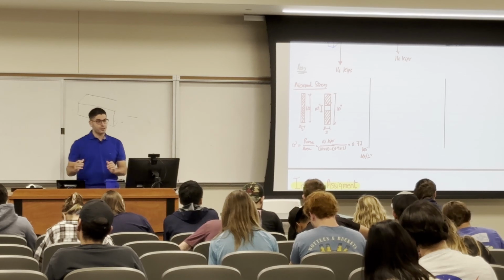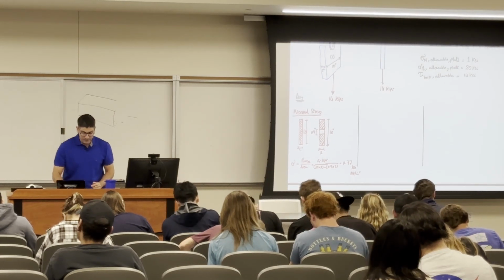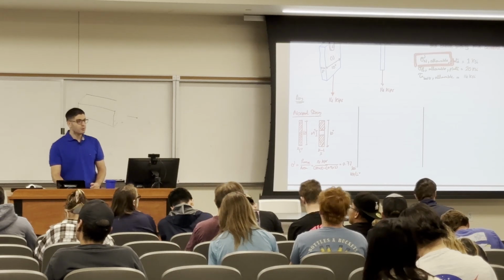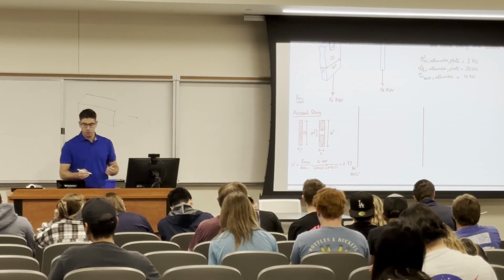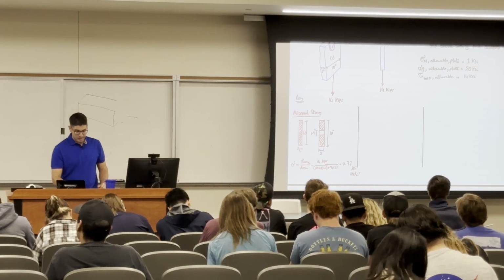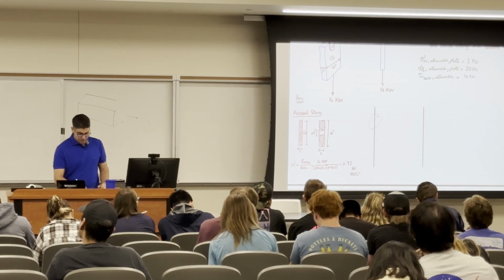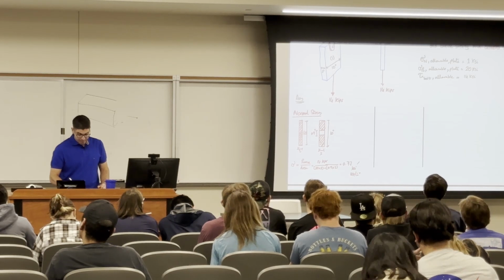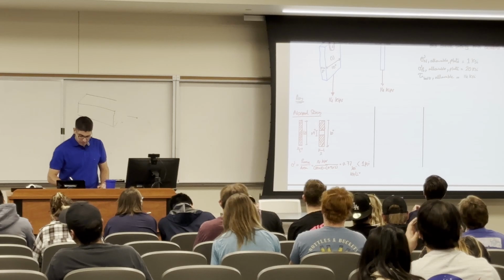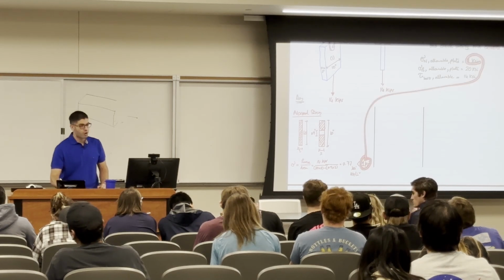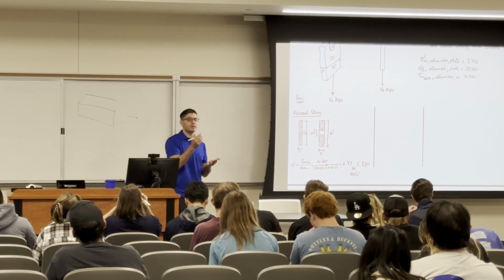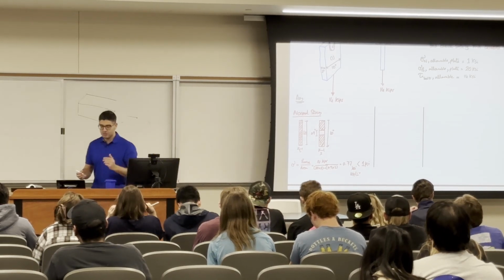Okay? I want to check the safety. So I will look at the strength, which is in the form of allowable. Allowable means accepted for the plate. So what's accepted is 1 KSI. Am I safe or am I unsafe? I'm safe because I am less than 1, because 1 is the 1 KSI here. Allowable means you are only allowed until 1 KSI, above which it's going to fail. So okay, now I'm safe in normal stress.